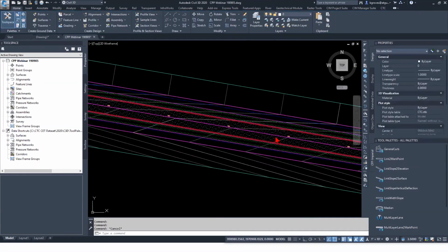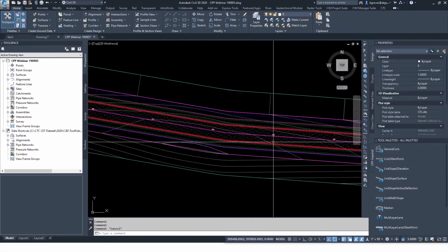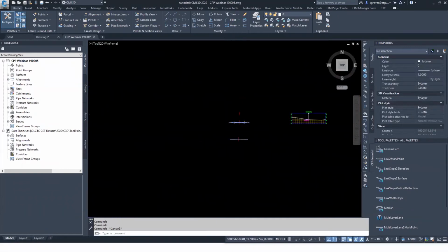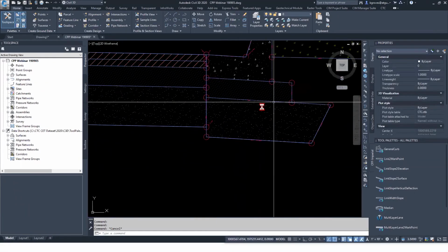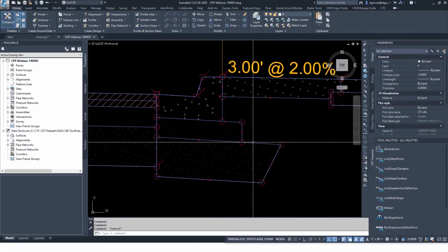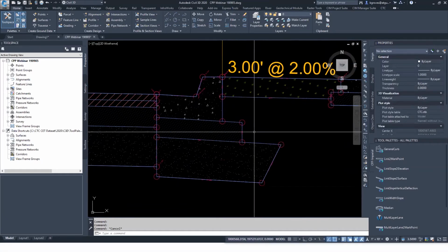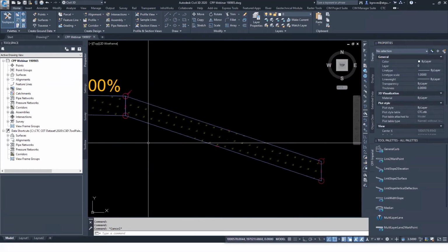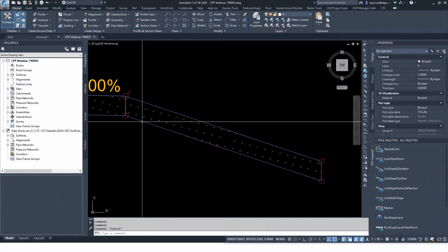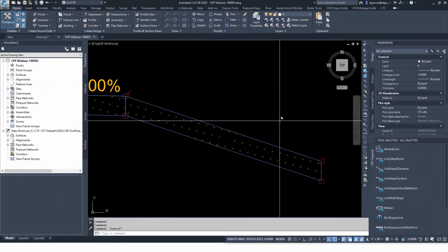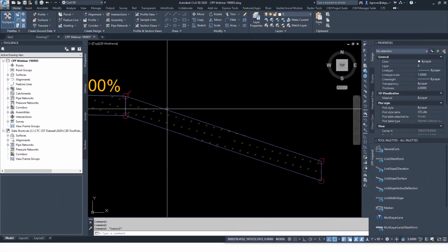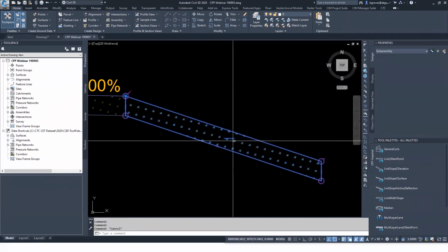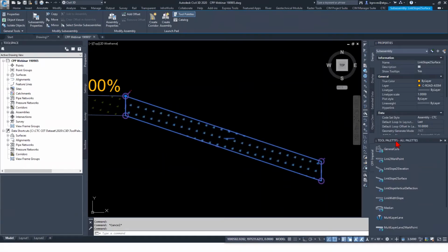So what this is going to do is redefine how things are set up. And I've been talking, I realize now, for some time about codes. Well, simply put, a code is how this information is being tracked through the software. So all subassemblies, all corridors, cross sections, the rest of that function off of codes. You've got points. When you connect 2 points, you get a link. When you have a closed set of links, you then have the opportunity to define a shape.